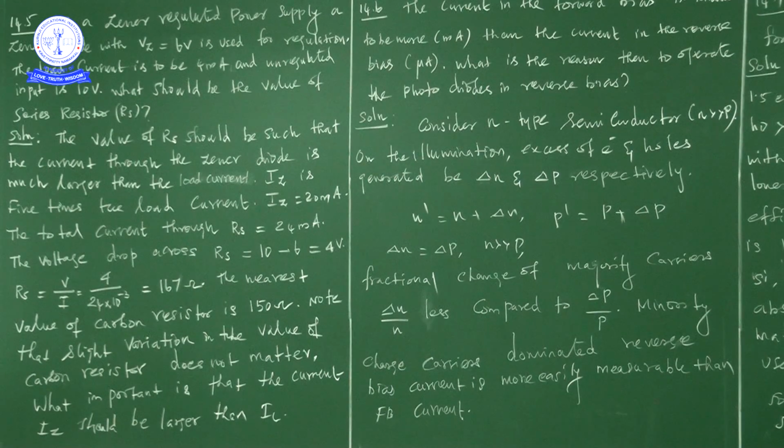If you want to calculate the voltage across the series resistor, Vs is equal to V minus Vz. V is the total potential we apply, and Vz is the voltage across the Zener diode. This is a very important common formula for calculating the voltage across the series resistor.